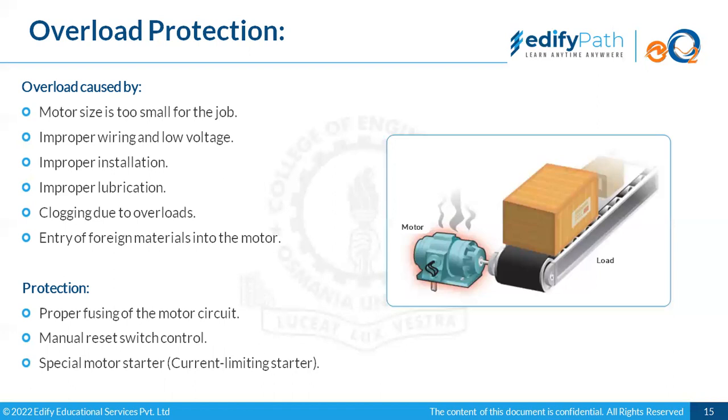If we have to run some process at a particular RPM, then we should install proper variable frequency drives, and there should be proper cutoff switches, so that if any abnormal condition arises, tripping could occur and take care of the protection of the motor. This way we can ensure the safety of the motor.